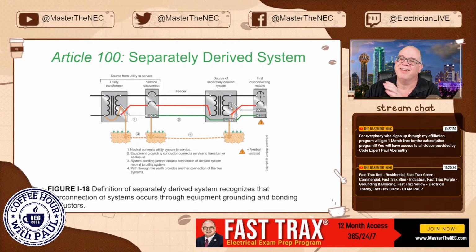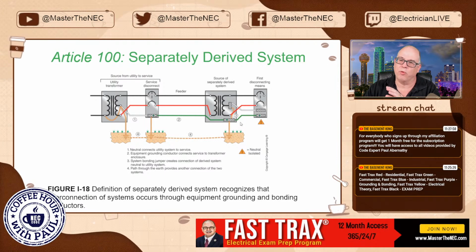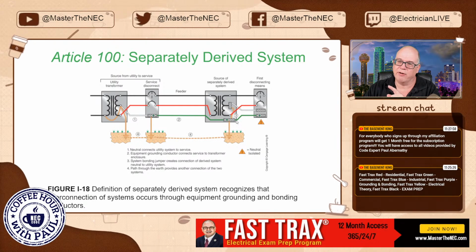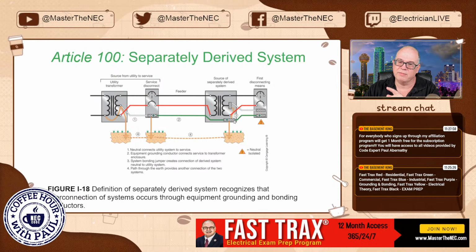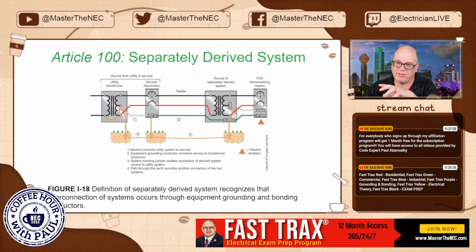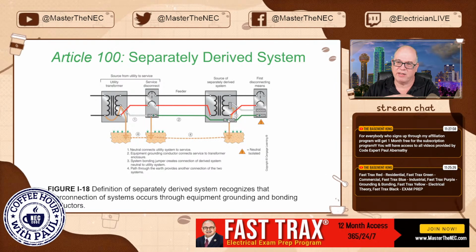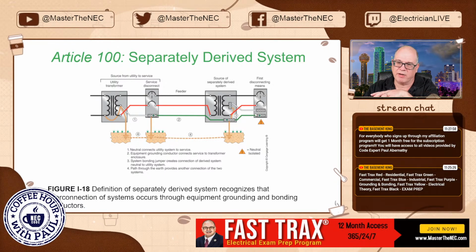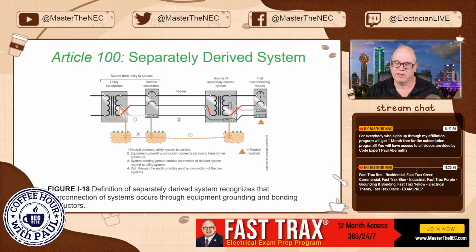All right. So here you see the secondary side, and you've got your 4 conductors. Here you see the system bonding jumper right here. Here is this conductor running up. There you go. And here's your first disconnecting means. And you see that they're isolated up here. So your system bonding jumper is done out here. Everything's done out here. And you've got your supply side bonding jumper run up here. Okay. So that's kind of a layout of how the separately derived system works.